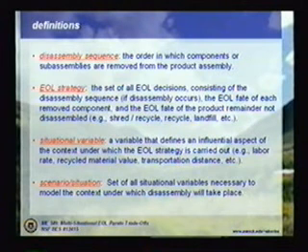The end-of-life strategy. So this is the set of all end-of-life decisions, including the disassembly sequence, as we've just defined, the end-of-life fate for each removed component, and the residual. So if I only disassemble half of the coffee maker, what am I going to do with each disassembled part, and now the residual? Am I just going to landfill that, or am I going to shred it and recycle what can be recycled from the fractional remainder?